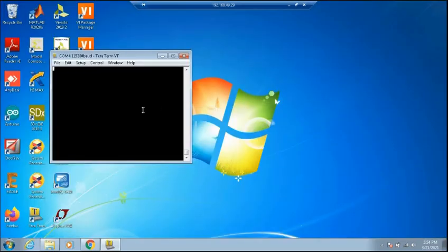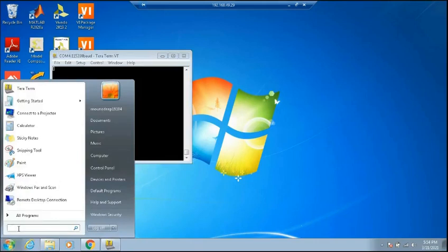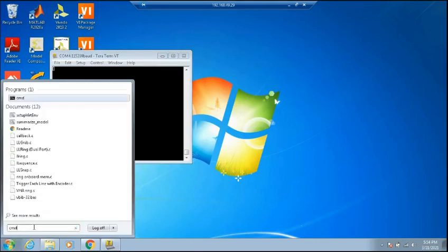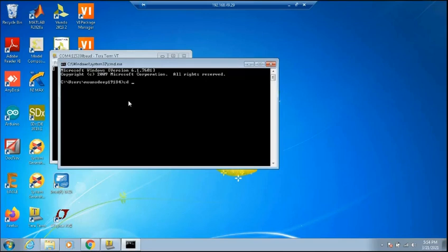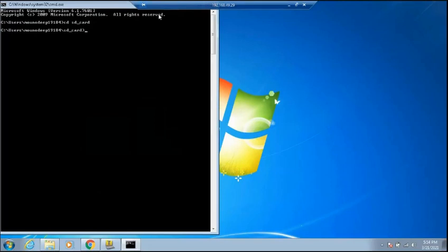Now we can transfer the files from the remote desktop to the board by using the PSCP command. For that, open the CMD, get inside the SD card folder, cd SD underscore card. Inside this folder, I have kept my files, and we use the PSCP command to transfer them. Just type in pscp -P, capital P, 22, and then the file names: boot.bin, readme.txt,